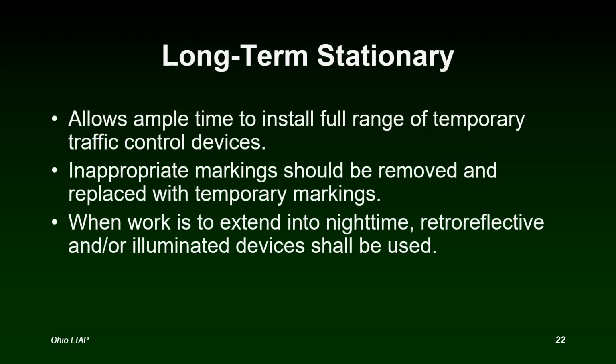So in these situations, you must allow ample time to install your full range of temporary traffic control devices. And most likely you're going to be using post-mounted signs, not your portable signs. And inappropriate pavement markings should be removed and replaced with temporary pavement markings. We talked about that in our first session. And then when work is to extend into nighttime, that's when we need to consider retroreflective and or illuminated devices to use.